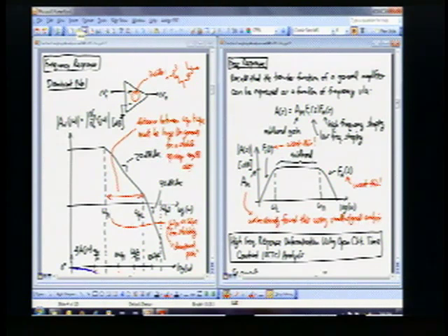frequency response. Okay, so just to start out here, you can recall that the transfer function of any amplifier, it could be an op-amp, or it could be any of the amplifiers that we're talking about based on transistor circuits, can be expressed as a function of frequency by way of this transfer function. So A of S, which is the same as this, right? I could have called this also A of S, where S equals j omega, right? S is just the complex frequency variable, is equal to some midband gain. And that's what we've been deriving up to this point. Okay, we've been doing midband gain calculations. That's the gain that you get if you look at this plot here, which is also a Bode plot.